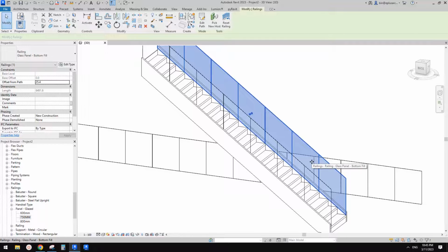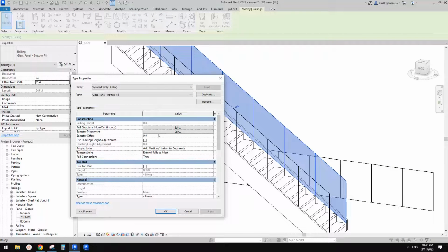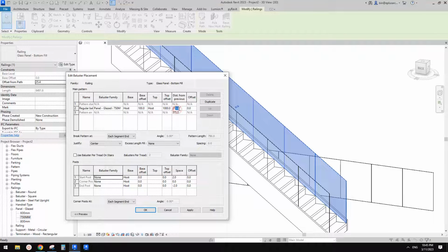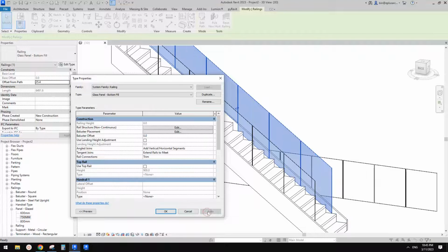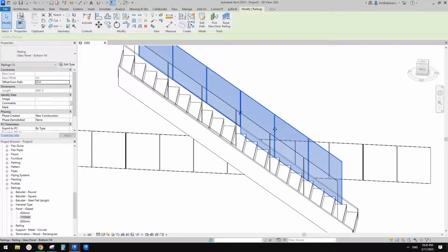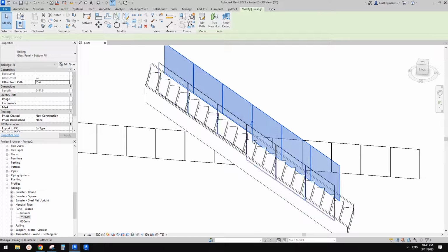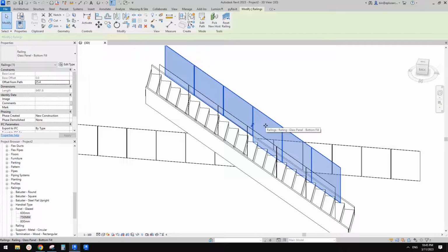I think instead of increasing it, of course you can increase. So for example, at 5 mil here, so 380. So you will be, hang on. I don't think this is a good way, because once you add it becomes 380, so the starting point of these panels changes. So you can see they're not the same size again. So I think let's just Control Z.